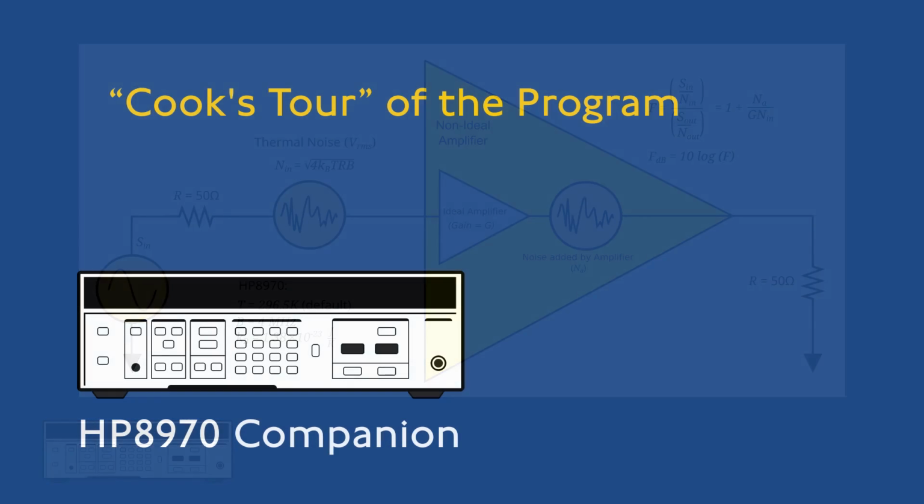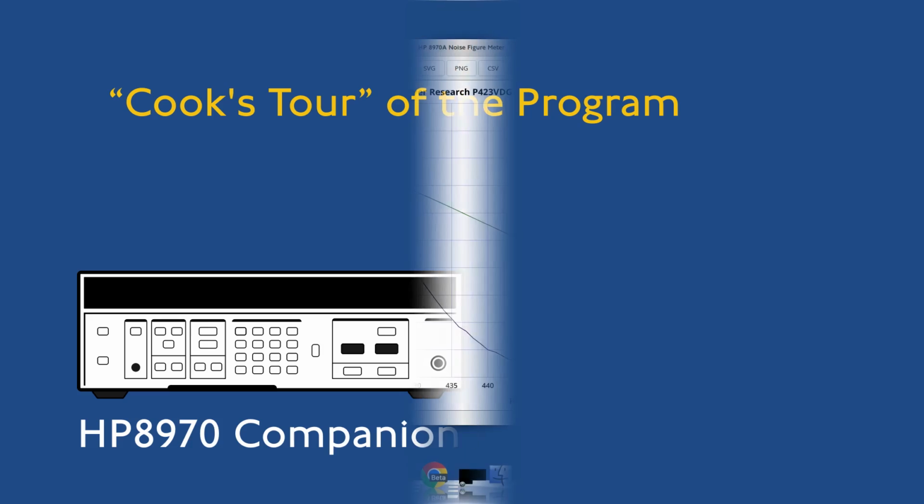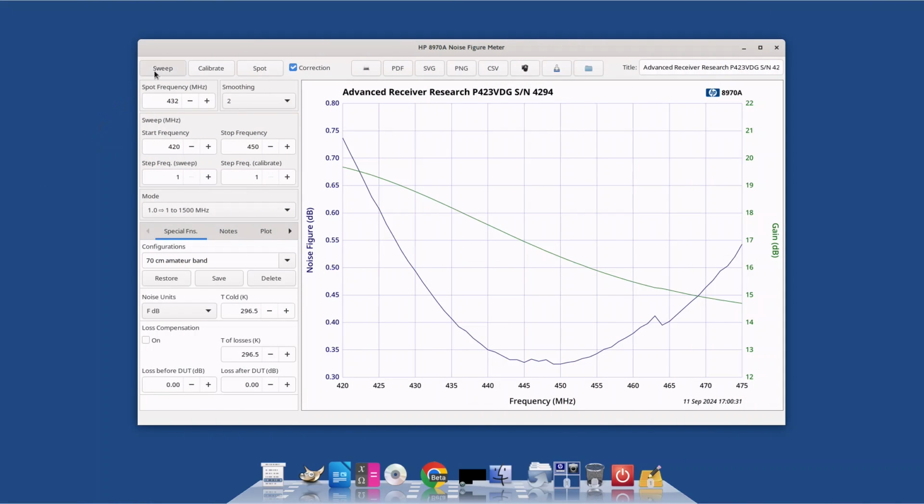Let us briefly examine the user interface and how the program controls and receives data from the 8970. Pressing the sweep button with a left mouse button click will trigger a single sweep, measuring noise figure and gain at frequency increments defined by the step frequency sweep setting. If the sweep button is pressed with the right mouse button, the button acts as a toggle and the 8970 will sweep continuously, overwriting previous sweep measurements until the toggle button is turned off.